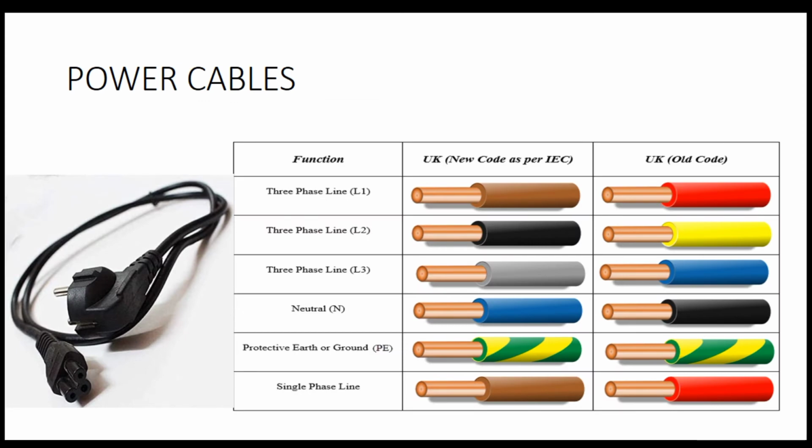Power cables. In addition to the importance of good installation of power cable from the main source to the socket outlet for the IT cabinet racks, the color code for cables is very important for the following reasons. 1. Avoid faulty connection during installation between the rack plugs and socket outlet, which will cause damage to the rack devices if they are connected to unacceptable PDUs, which can be a huge mistake. 2. The availability of load balancing between phases and selection of a suitable phase for loading. 3. It facilitates the maintenance process.